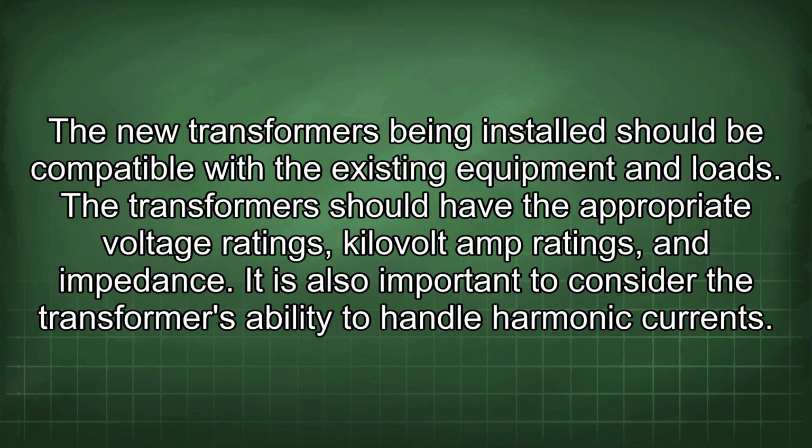The new transformers being installed should be compatible with the existing equipment and loads. The transformers should have the appropriate voltage ratings, kilovolt amp ratings, and impedance. It is also important to consider the transformer's ability to handle harmonic currents.